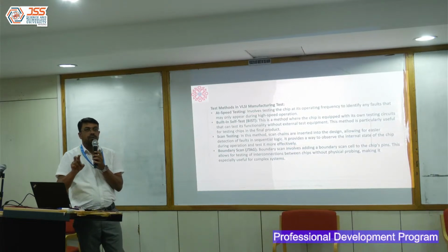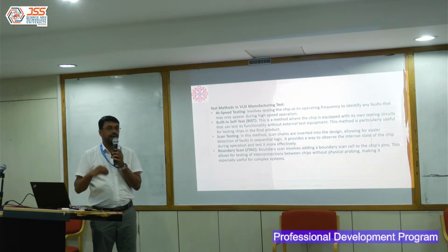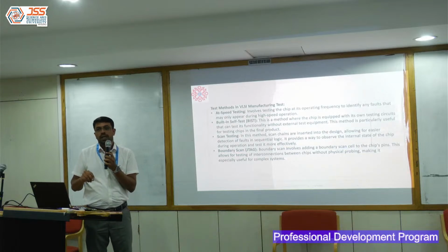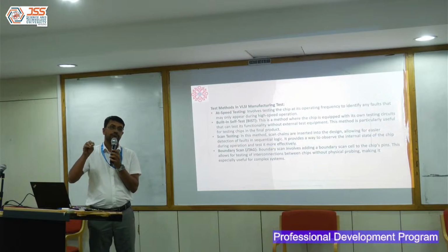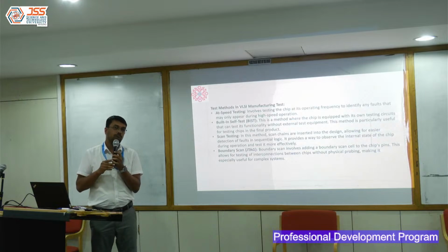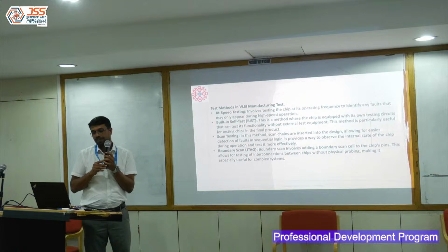You have read about PLL, phase locked loop. Typically, for a chip, there is something called as a functional frequency. A chip would be designed to operate at a particular frequency. Typically, most of the advanced chips use a functional frequency in some gigahertz, 1.5 or 2 gigahertz.